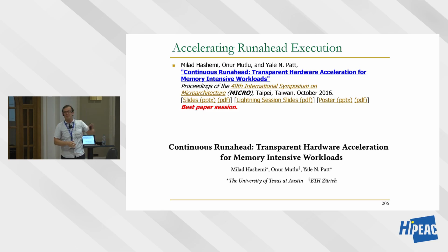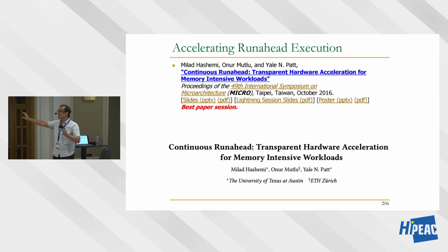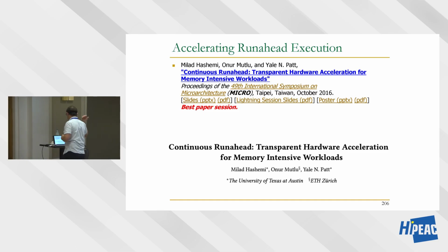Here, what we do is, if the processor is going to stall, why don't you ship the code speculatively to the memory controller, and the memory controller does the prefetching for you, and the processor can keep going on executing the main program while you're doing prefetching for the program in the memory controller. So this is actually a really nice way, and it actually increased the potential of prefetching much better.